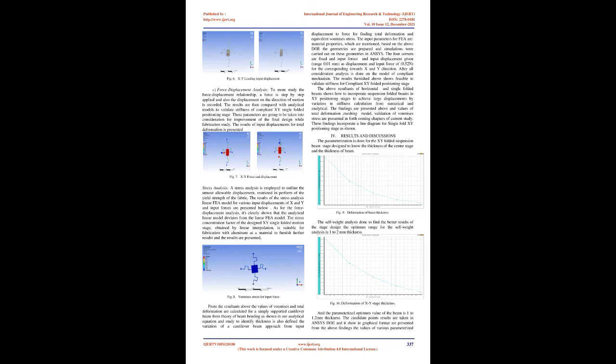Stress analysis. A stress analysis is employed to outline the maximum allowable displacement, restricted as a function of the yield strength of the material. The results of the stress analysis, linear FEA model for various input displacements of X and Y and input forces, are presented below. As for the force displacement analysis, it is clearly shown that the analytical linear model deviates from the linear FEA model. The stress concentration factor of the designed XY single-folded motion stage, obtained by linear interpolation, is suitable for fabrication with aluminum as a material to furnish further results, and the results are presented.